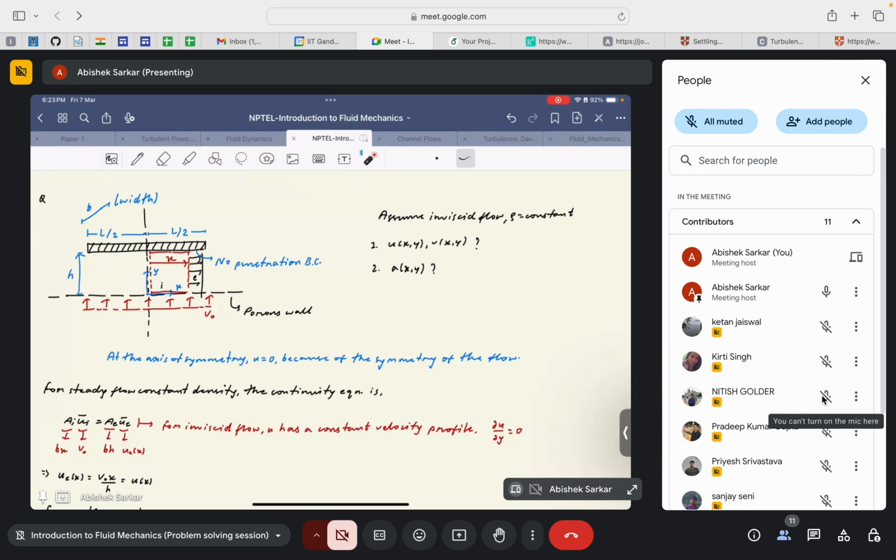Here we are again introduced to the concept of boundary conditions. We discuss it elaborately when we solve specific cases of the Navier-Stokes equation. But right now, boundary conditions basically mean the value of velocity or pressure at some particular boundaries of the geometry. At the bottom surface of this stationary plate, the fluid cannot pass through, because it's not porous, it's a solid surface. So the y component of velocity at this point would be 0 because the flow cannot penetrate through this plate, and that's why we term this the no penetration boundary condition.